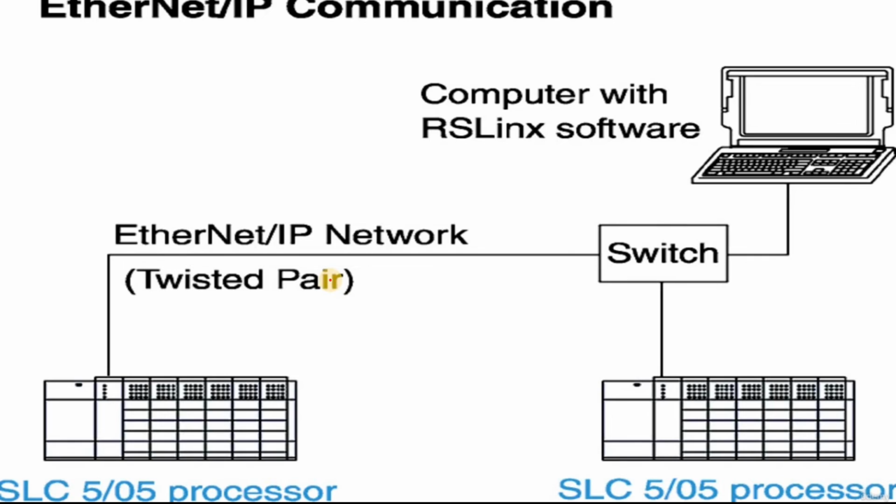In most cases, the RS-232 and Ethernet communication cables are preferable. Here in this image you can observe we have used the Ethernet cable. If you are using the Ethernet cable, you must be aware of the IP address of our system and the PLC as well.